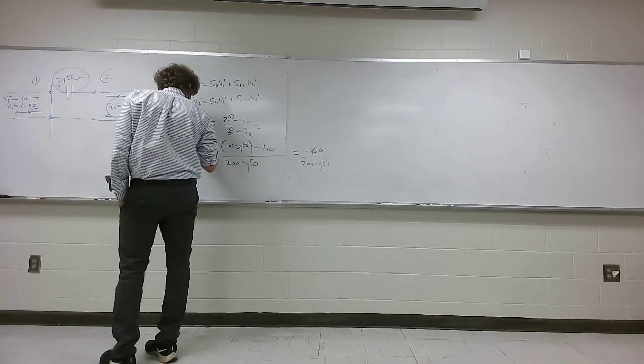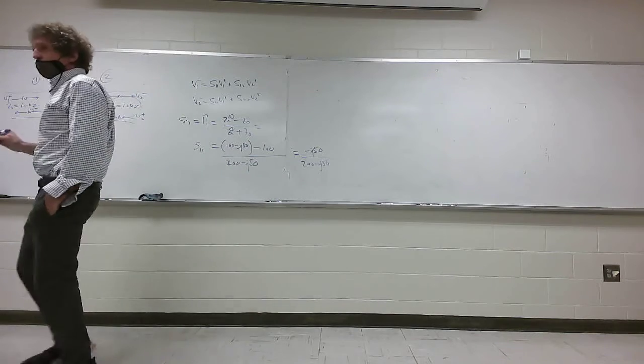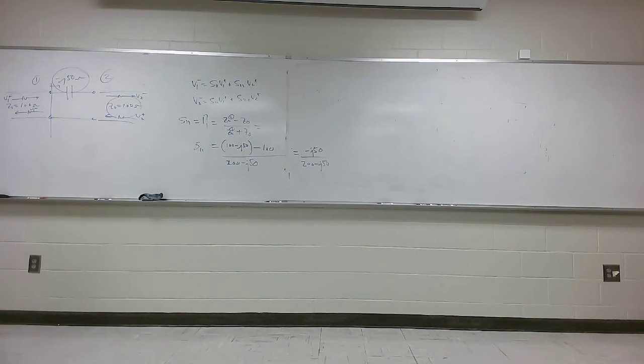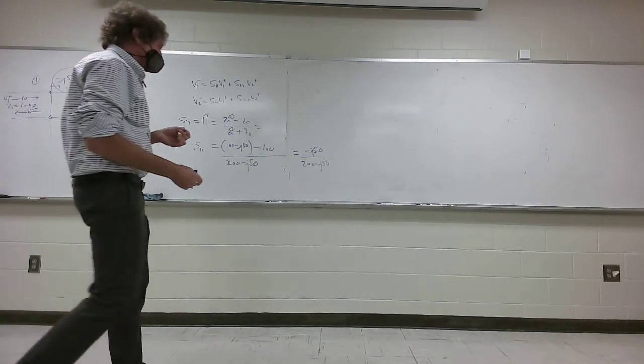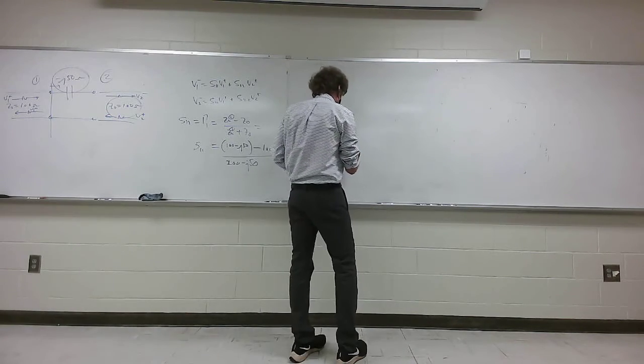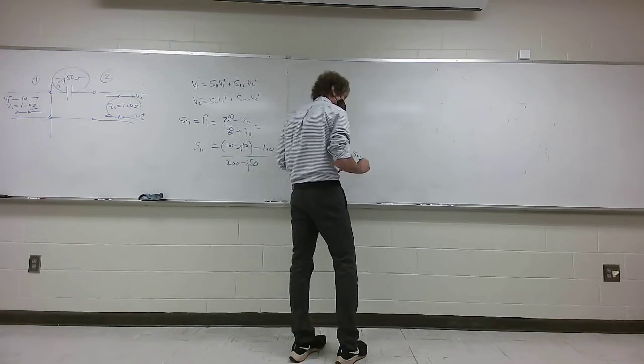Now there's something I didn't say, but I bet you know what it is. What is S22? And give me your reason for it. It's the same as S11. She's absolutely right, because if you look at it either way, it's the same. It's called a symmetric matrix or symmetric S parameters. Whatever they are in port 1, just reverse it. It's the same thing in port 2 as well. Y'all follow me? So you only have half the work. So S11 will be equal to S22.